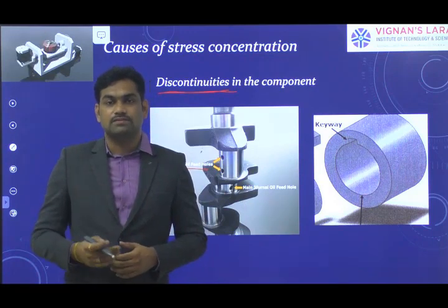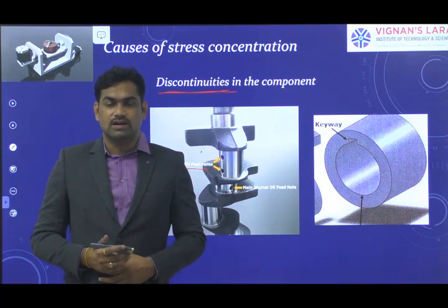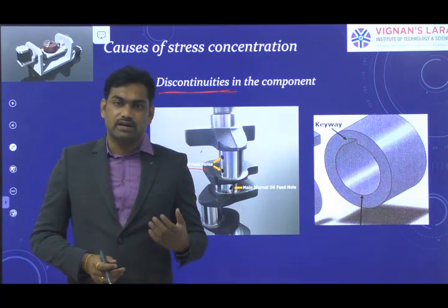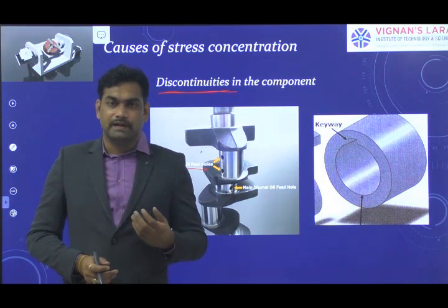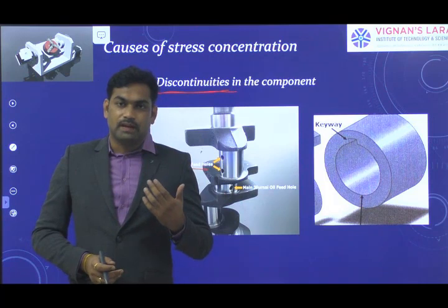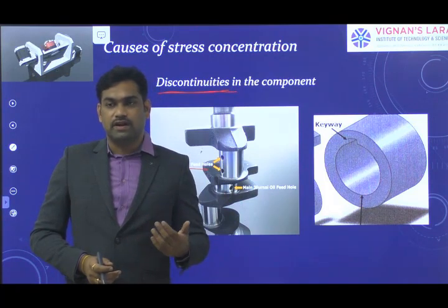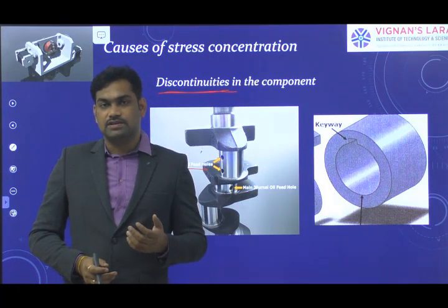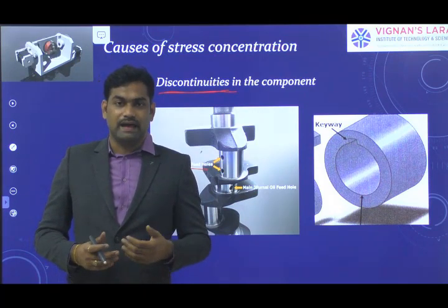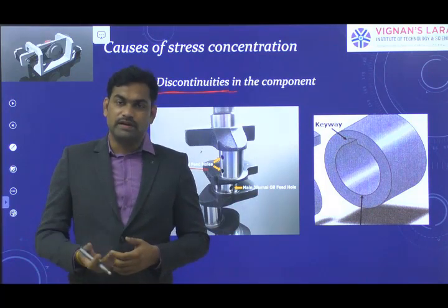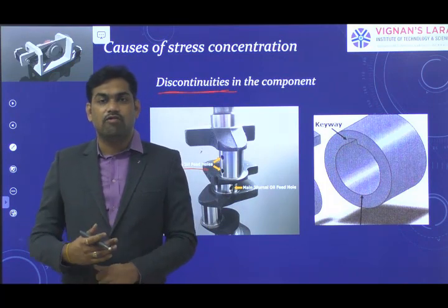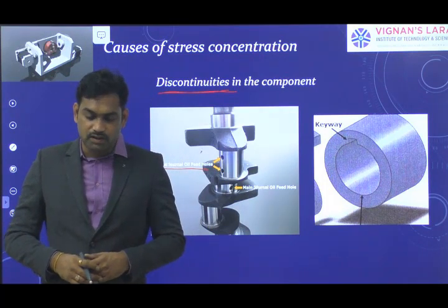Whenever the maximum stress is induced at some particular areas, for example surface defects like cracks, if the stress is concentrated more in the vicinity of the crack tip, it causes propagation of the crack whenever load is applied on the machine component. Beyond the strength the crack can withstand, the machine component is going to fail in a brittle fashion. So we need to avoid stress concentration at these particular areas.